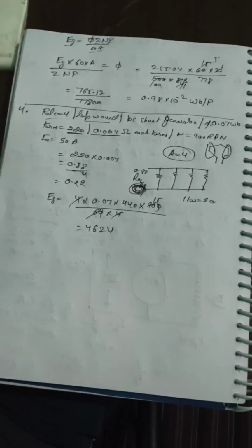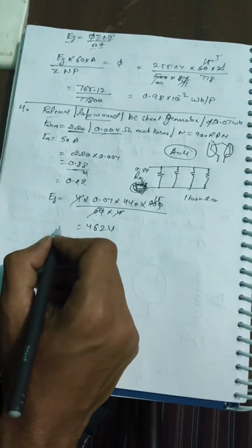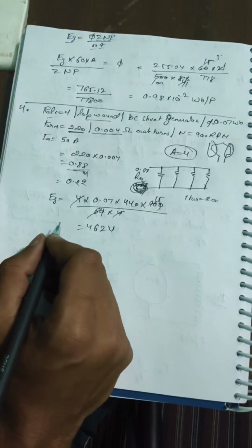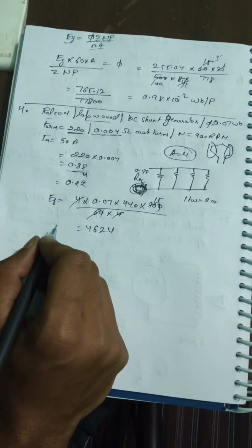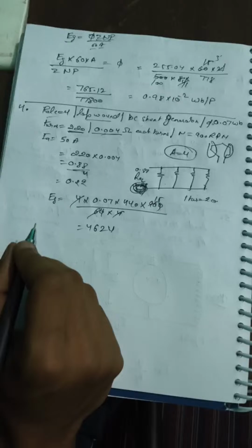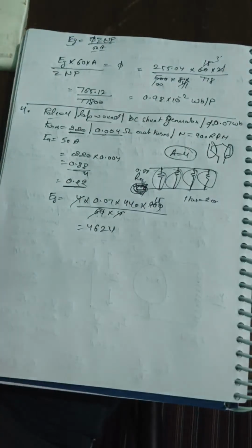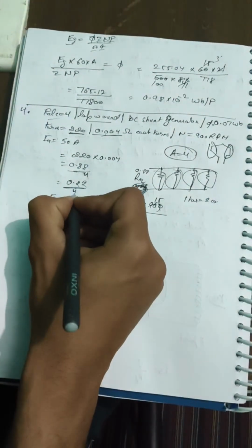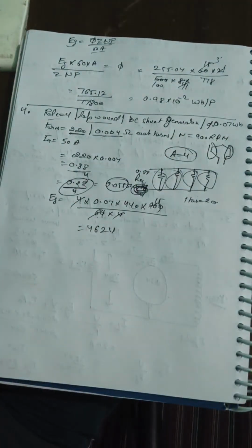So now we have the generated voltage. Guys, I'm thinking of something, that here the actual resistance of the armature winding is not just this. As we see, the number of poles also affects how much resistance actually lies there. So it will be divided by 4 two times. So now the resistance will be equal to 0.055 ohm actually. Firstly due to parallel paths and second due to the number of poles.